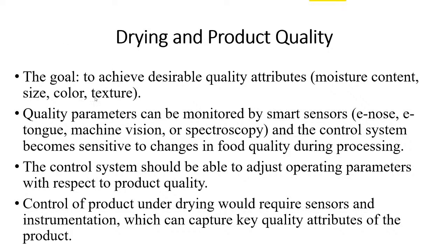In drying, to optimize these quality attributes, we have to find ways to monitor them during the drying process. In the past, we only monitored the temperature. We may also monitor the humidity, but we didn't monitor any of the quality aspects during the drying operation. And for quality aspects, we need smart sensors to help us in monitoring the quality attributes.